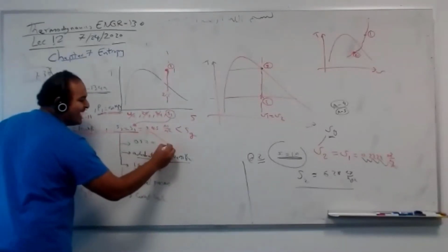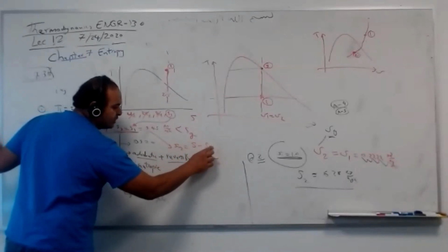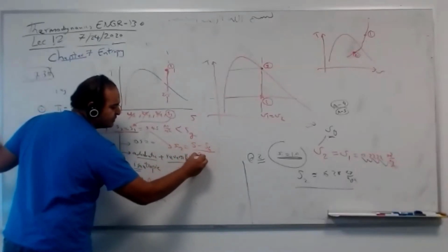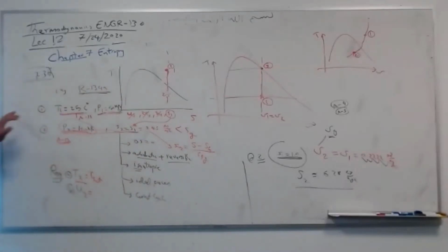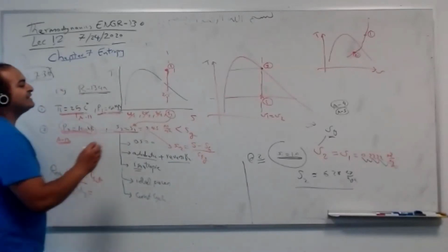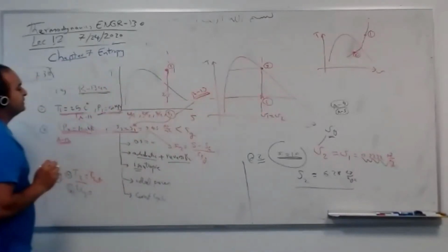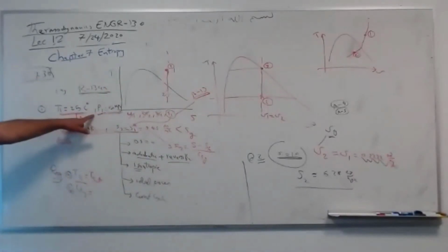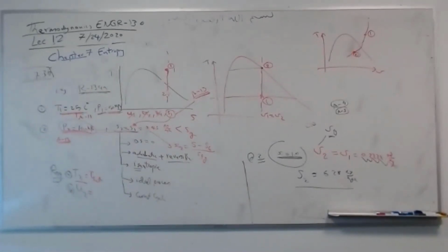You can get from this X2, which is S minus Sf over Sfg, at state 2. So at state 1, you can get S1 from which table, guys? A13. This is table A13 because it's superheated. This and this are superheated, so go to table A13. Open with me table A13 at pressure 600 and temperature 25 Celsius. Let's do it together.